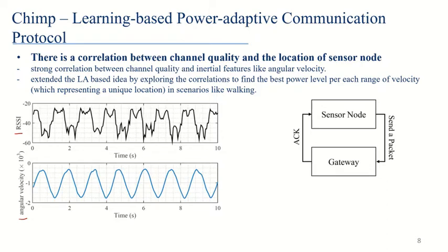The motion pattern can be measured by an accelerometer, but here I used a gyroscope, because an accelerometer is subject to outer forces like gravity, and it is noisy. You need to do more processing, but the angular velocity measured by a gyroscope is quite smooth. You don't need to do much processing there.